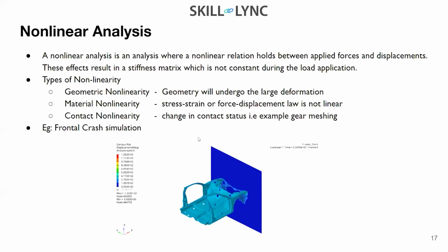Again, what is non-linear analysis? In a non-linear analysis, a non-linear relation holds between your forces and displacements, which you will see with respect to time. Crashworthiness is a non-linear dynamic analysis. Why am I calling it dynamic? In crashworthiness, all the crashes in a car happen in a couple of seconds. All the failures and damages happen in a couple of seconds.